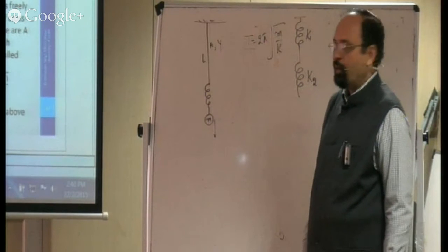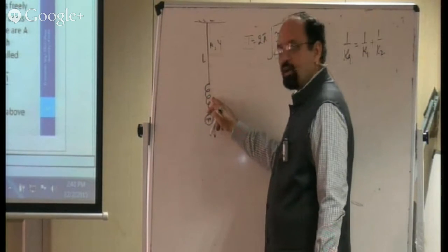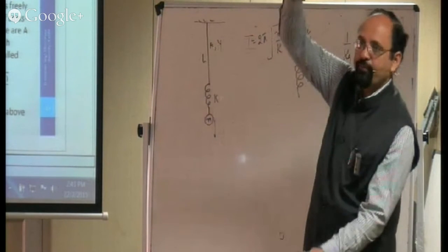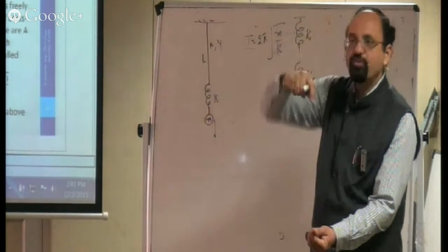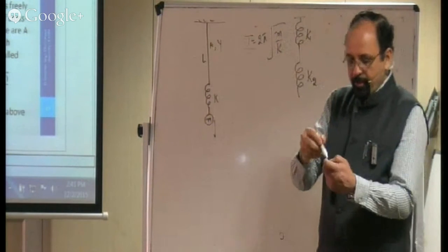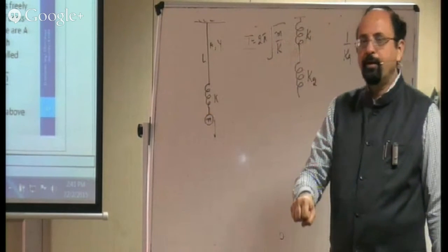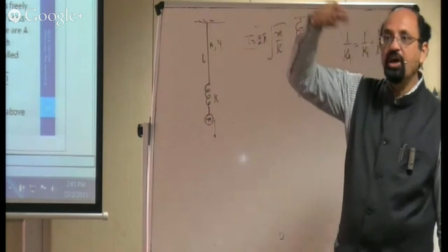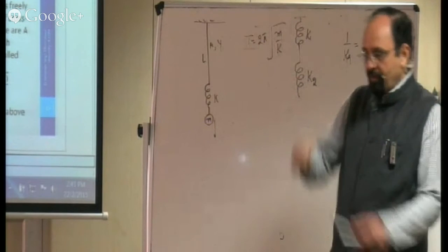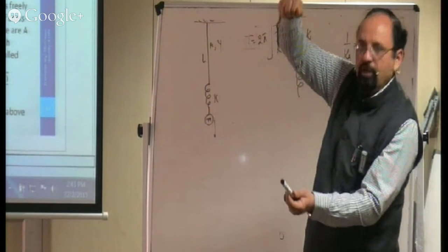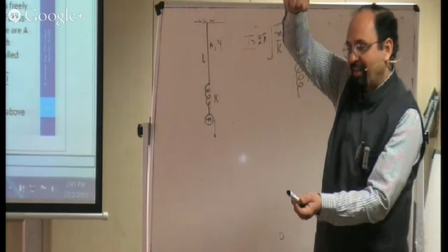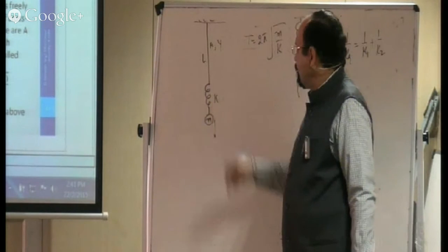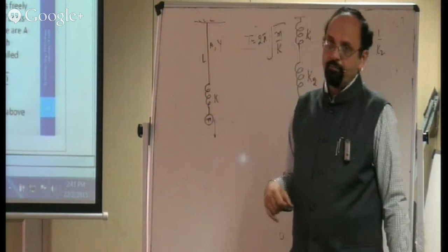That is important. I have this wire, I have this spring also. The spring has a spring constant k, but this wire also will stretch because of the load which you are putting. It's very interesting: when this load is going down, it is adding tension in the string, and when it is moving up, it is reducing the tension. If I make the string elongate, I'm putting stress in it; when I'm taking it back, I'm reducing it. It's just like a spring. So I will treat this wire as a spring.